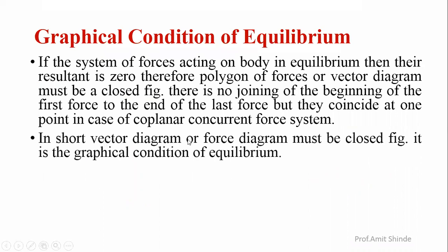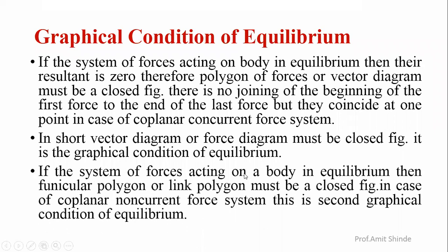In short, the vector diagram or the force diagram must be a closed figure. It is the graphical condition of your equilibrium. If a system of forces acting on a body is in equilibrium, then the funicular polygon or the link polygon must be a closed figure in the case of a coplanar non-concurrent force system. This is the second condition of your equilibrium. For the non-concurrent force system also, it must be a closed polygon.